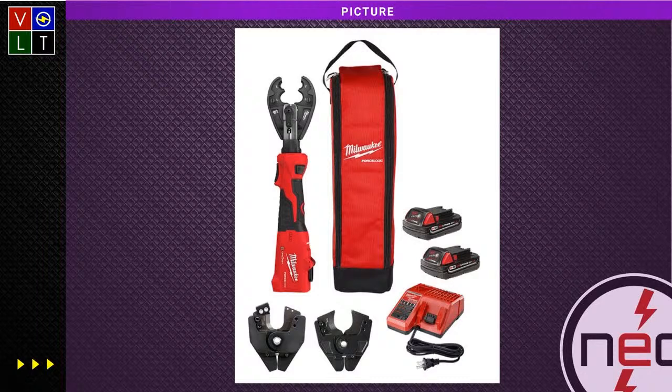Now, I will give you a little history lesson. If you put the die in there that says number 8 and you crimp a number 6, and then the inspector shows up and says you have a code violation, then Lemonhead knows all about this. They might call you on the radio and say, you got to go fix that connection. And I thought that was really cool about these crimpers.